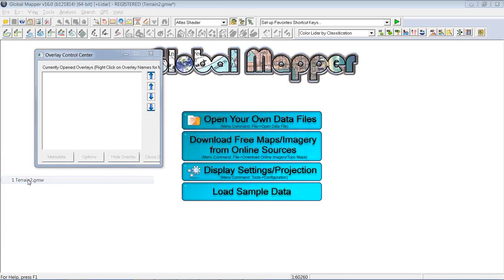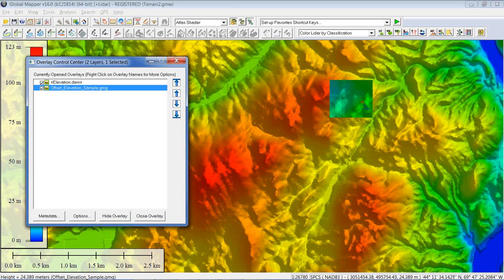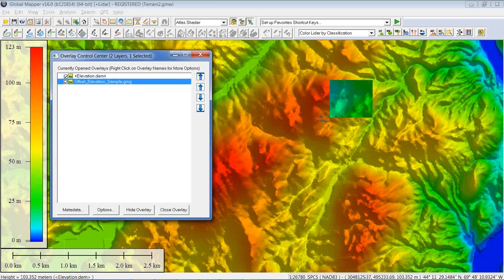Okay, thanks, David. So I'm going to go through 3 different types of volume calculations that you can do with multiple terrain grids. So this is the same workspace we had before. David showed you the path profile through this separate elevation grid, and this is lower. You can tell by the colors that it's lower than the larger terrain here. So we're going to go through measure volume between surfaces, then we're going to calculate a pile volume, and then we're going to compare and combine surfaces. So I have the workspace open.